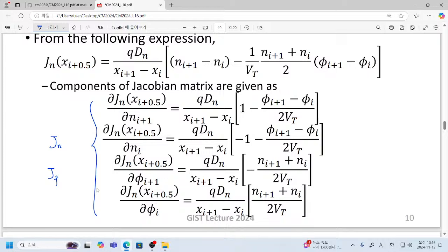So please note that when you have some convergence problem, first of all you have to see the position where the error occurs, and if the Jacobian looks perfect and the residual looks perfect, then please check the consistency between them. Are they consistent?